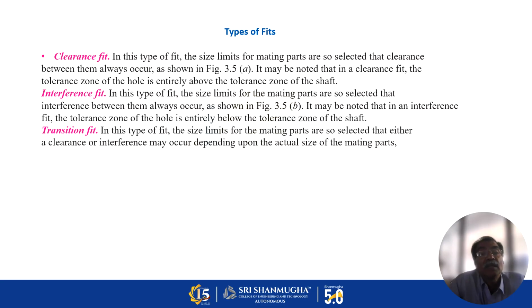In the clearance fit, the tolerance zone of the hole is entirely above the tolerance zone of the shaft. The difference between the minimum size of the hole and the maximum size of the shaft is known as minimum clearance, and the difference between the maximum size of the hole and the minimum size of the shaft is called maximum clearance. The clearance fit may be a slide fit, easy sliding fit, running fit, slack running fit, or loose running fit.